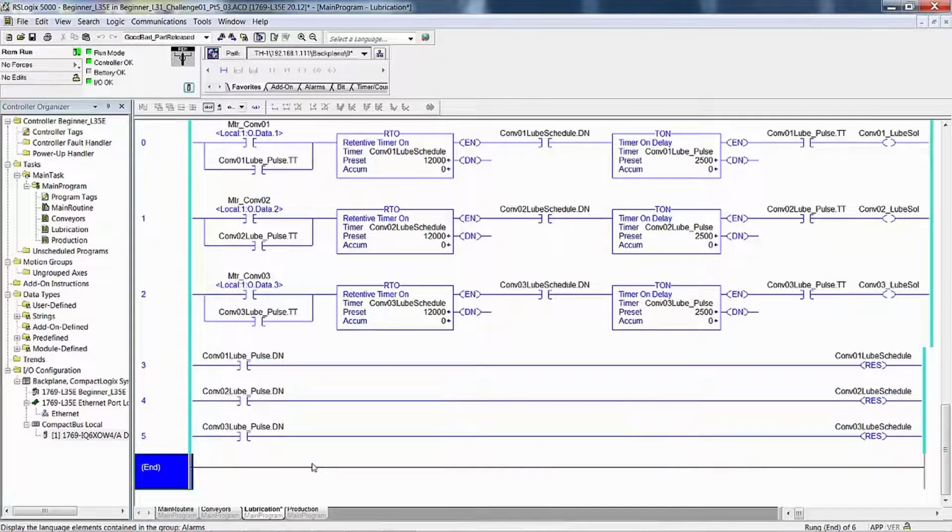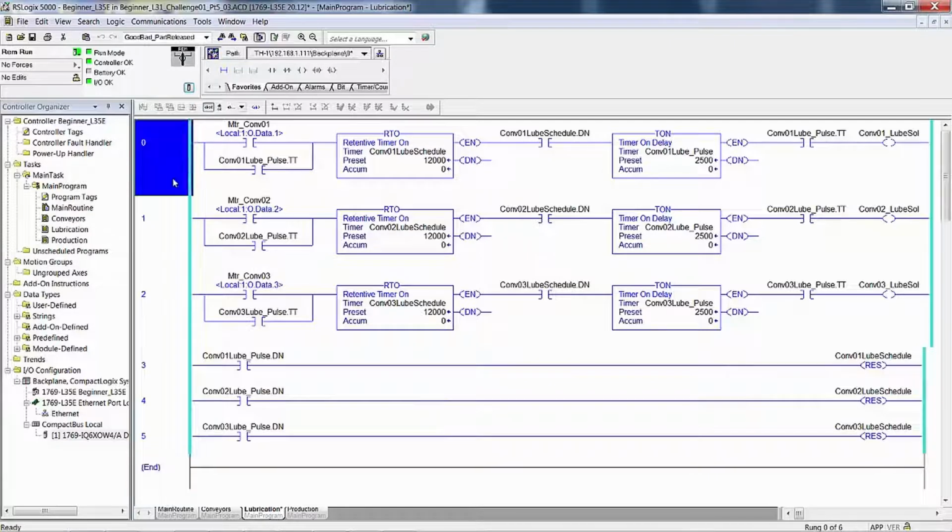Now, there isn't much more that you could do to, well, you could combine the reset. We could make the 3 rungs just a little bit more convoluted. You see this done bit right here? We could branch around here. Branch around and move the reset and the done bit right here. But I don't know that it would make the code any more readable. However, it does make it more conclusive. So just for grins, let's do one.